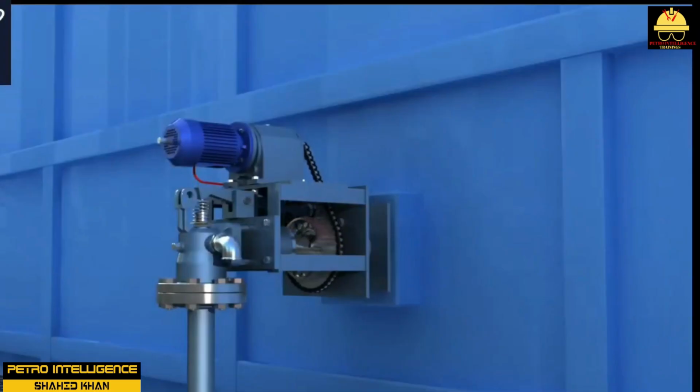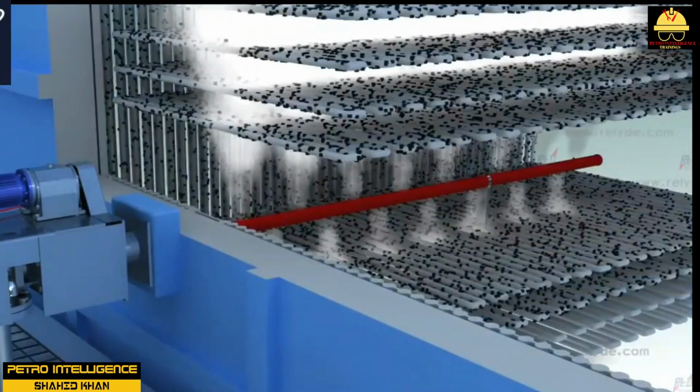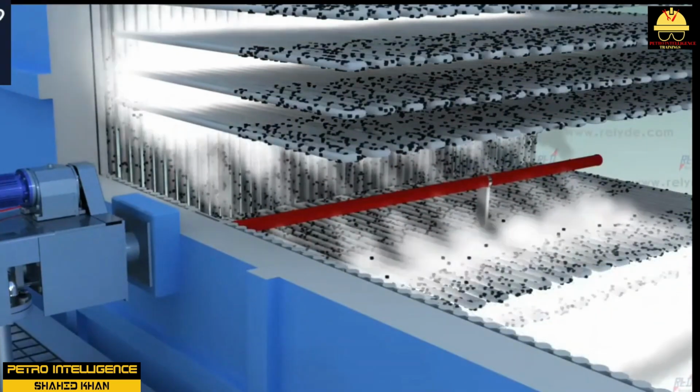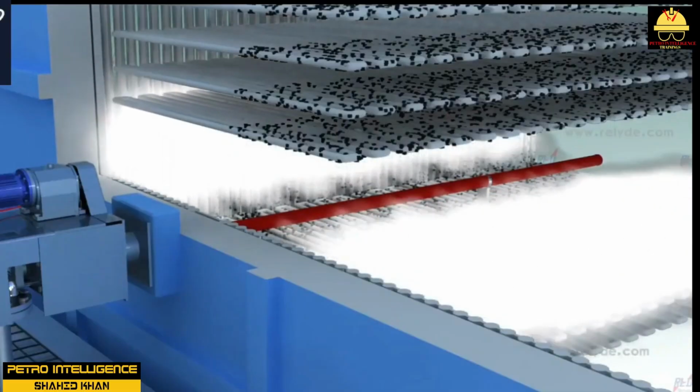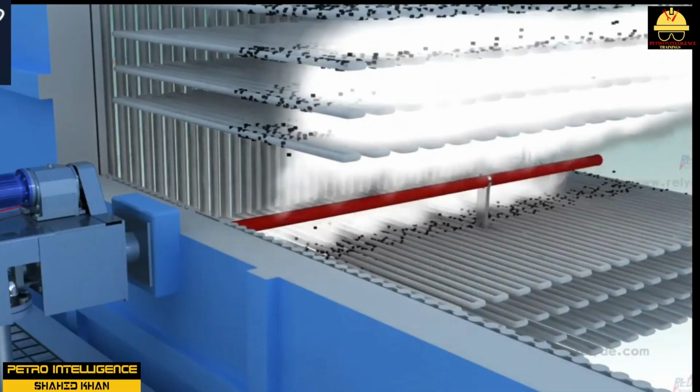Furnace wall blowers have a very short lance with a nozzle at the tip. The lance has holes drilled into it at intervals so that when it is turned on, it rotates and cleans the deposits from the wall in a circular pattern. Soot blowing continues until a preset timer goes off.